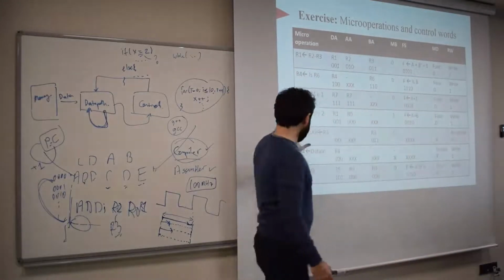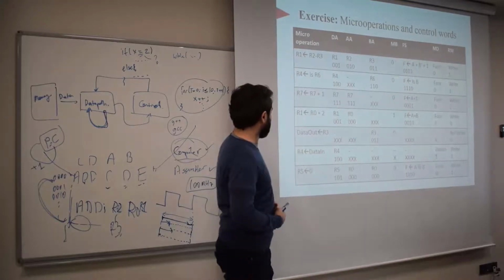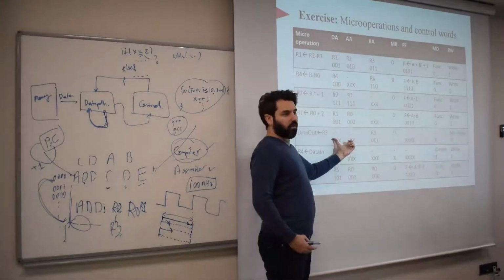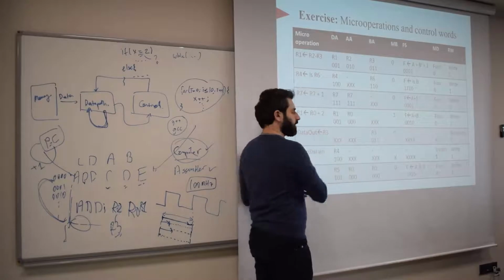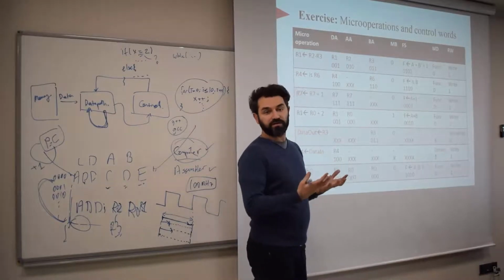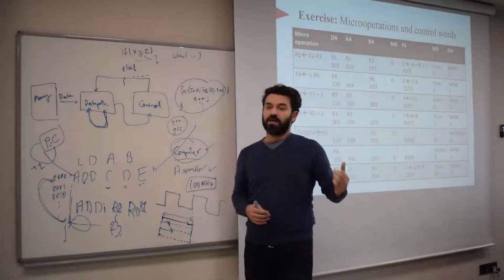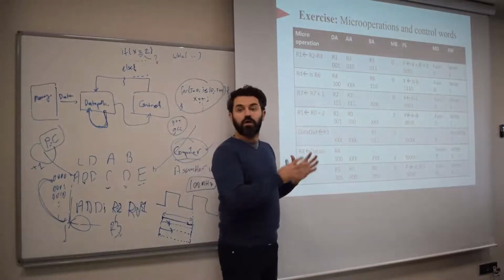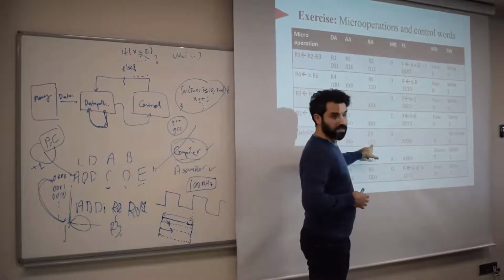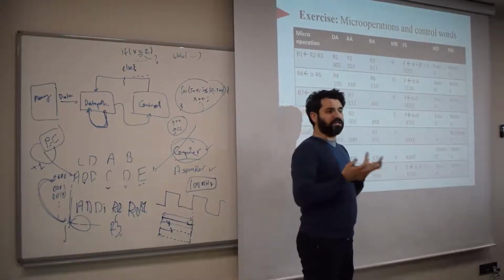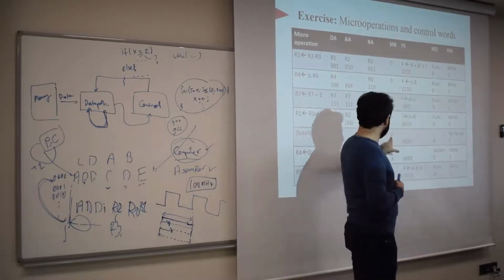Okay? Now these two are very important because these are allowing us to read or write something from the memory or to memory. You see that the operands are all don't cares. Okay? The only thing that we care about is R3, that is the register that contains the memory address. That memory address is on B because again, this is based on our data path. Data in, data out, only connected to the source B, not source A. That's why we have this R3 selected, 011. Whatever that R3 contains is our address. So we have to use it as an address. There is no constant, nothing about constants happening.